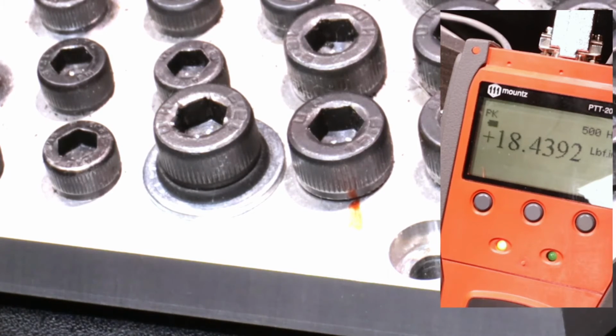For some of the higher torque values, you could do it with a digital wrench that may have a torque and angle sensor within it. That way you can just set your angle, turn your fastener anywhere from 5 to 10 degrees, and see what value you get. We also have rotary style sensors that have an angle in them as well, so you're able to see what those values are at a specific angle using that type of sensor.